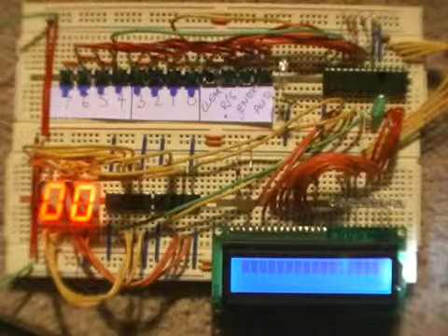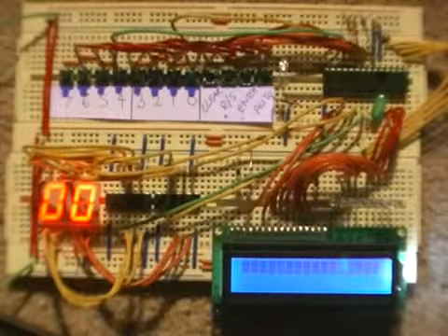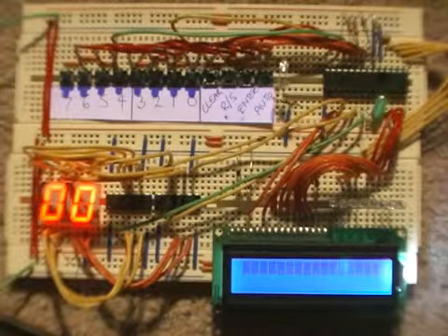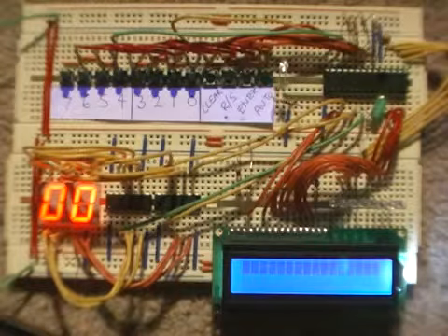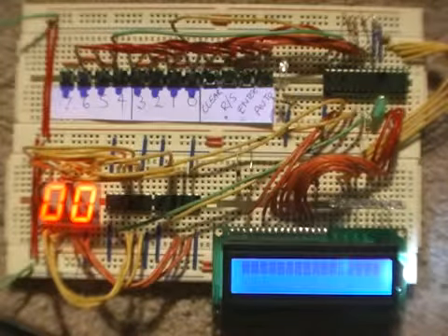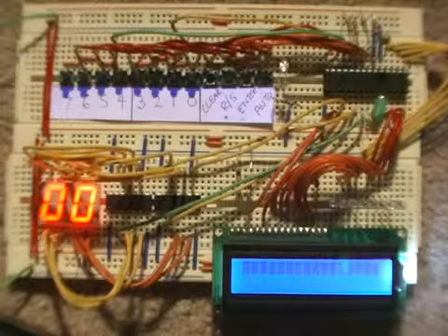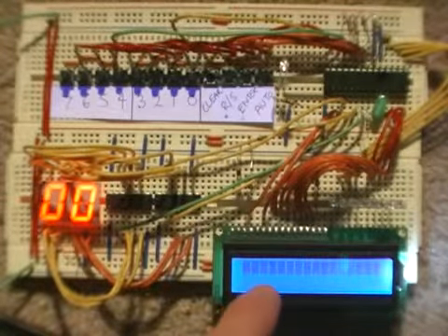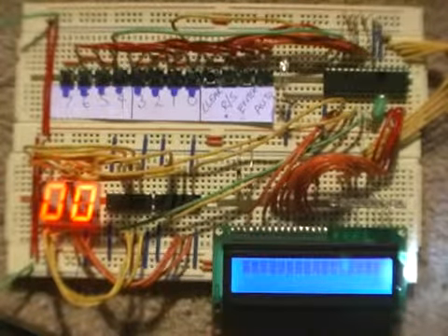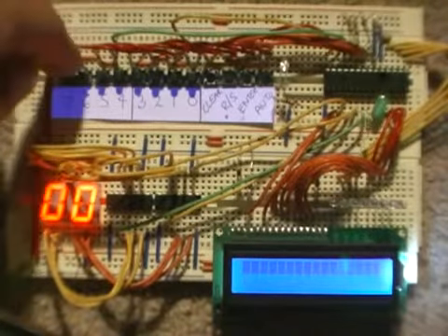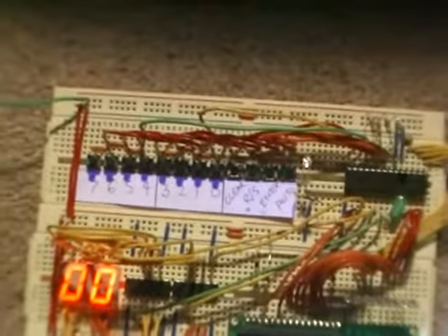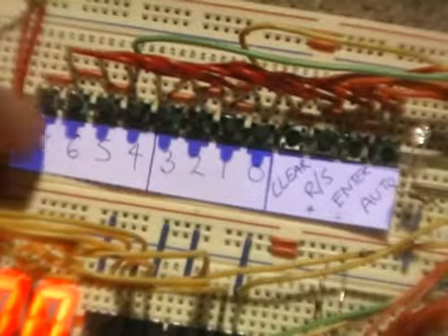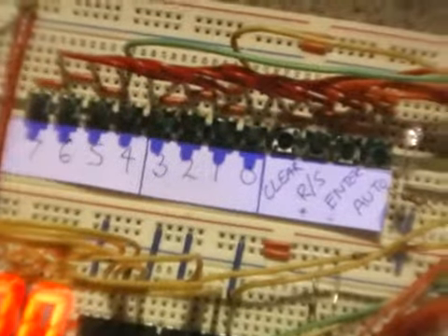Right, this is something I've made intended to help those who wish to interface an LCD display with a PIC microcontroller. All this circuit on this breadboard does is teach you the basic commands and codes that this LCD, in particular the one I'm using is a 44780 LCD, uses. I've got a series of switches up the top. It's just 8 switches for the data line bits, so bit 0 right through to bit 7.